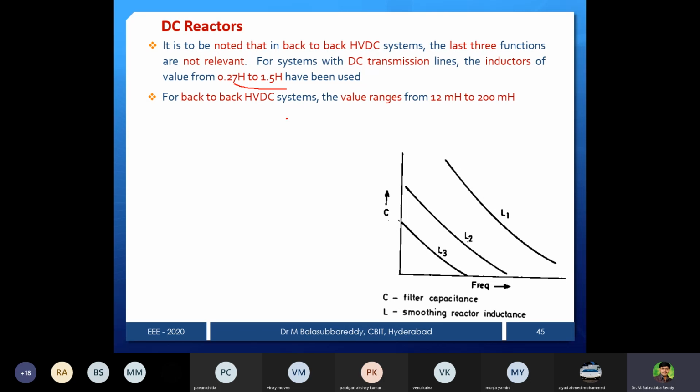In a voltage source inverter, if any commutation failure takes place in leg 1, leg 2 or leg 3, that means 1 and 4, 3 and 6, and 5 and 2, and devices in the same leg conduct at the same time due to commutation failure, then automatically in the VSI the input side has a low or negligible impedance.